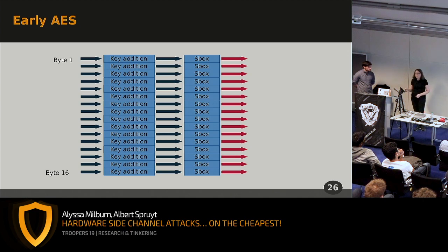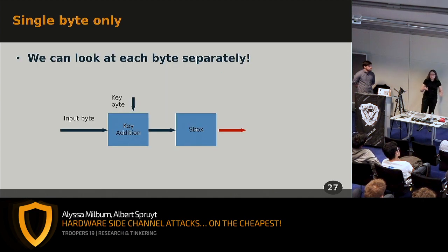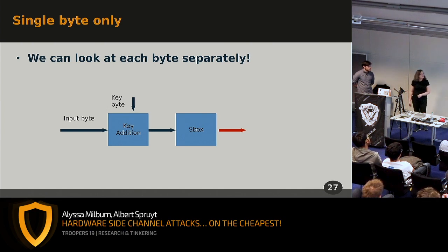by byte. So if we're looking at the first byte of the input, and remember, we control the input because you can send commands, for example, if you can control the encryption or decryption on the device. If it's firmware, then you can simply set the firmware on the device. You can reflash it to be whatever firmware you want, set it upgrade images. You control the input. And the key byte being used is the one corresponding to the input. So the first byte of the input is the first byte of the key. So we can do this step by step.